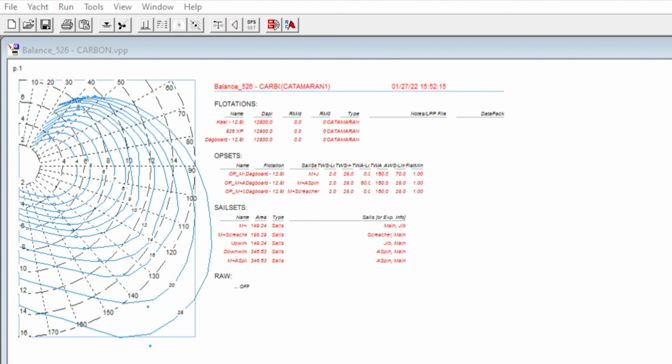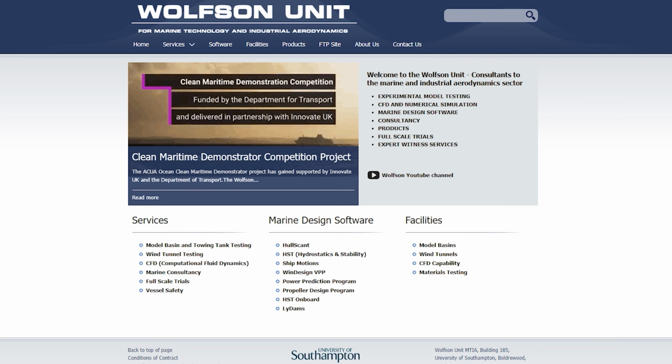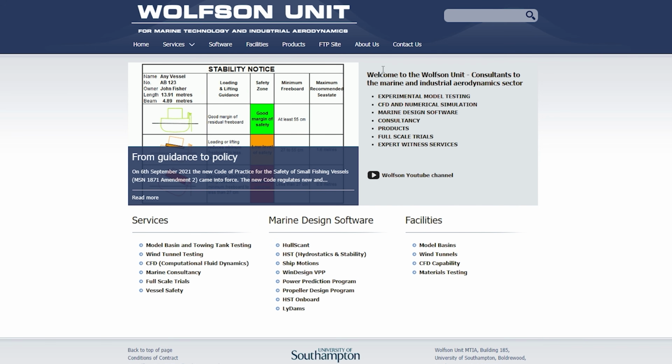And a VPP has become a complicated tool. There are only a few commercially available tools that are trusted in the marine industry. And the very high-end designers have their own versions of those VPPs that are based on the research work we've been able to accomplish in America's Cup or Volvo races. And so the testing we do improves those tools all the time until we have a tool that we believe in. And we use that tool to then estimate the performance of a boat.